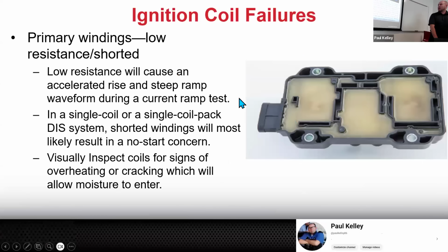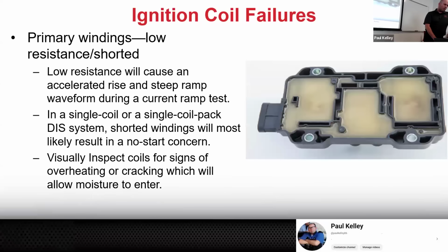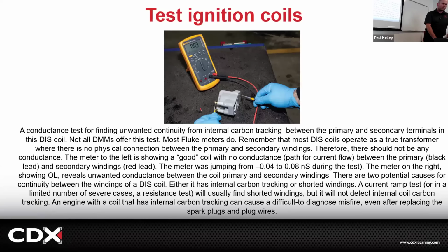If you were to look at that on a diagram, that would be this secondary coil getting shorted right here to the actual housing. Cool. A lot of times those housings are grounded. Not all the time, but a lot of times. So these are all tests, easy tests. What tools have we been using? It's the meter. You guys can use the meter, right? You can do all those tests.